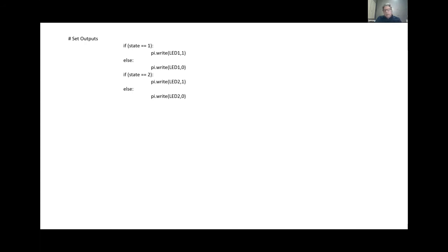Things like writing a machine status to a database where I can remotely monitor a machine, etc. I might only do that every 10 seconds or every minute. So I'll have a very large count number there. So again, I don't need to do everything, every loop. Whereas inputs and outputs and driving servo motors and VF drives and things like that, I do them every 10 milliseconds. So it seems to me to work quite effectively, this concept.